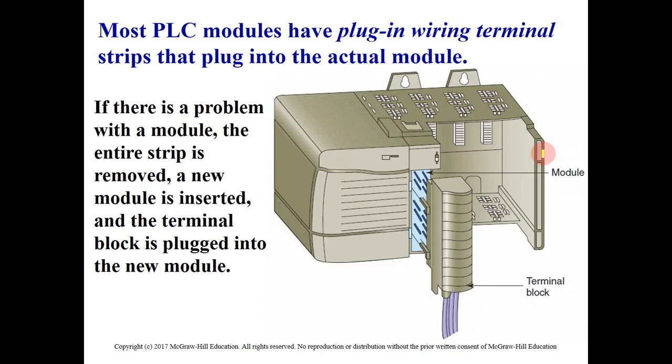This is just a 3D representation of the module, the modular PLC, and you can see here this is the empty place. In this empty place, we are going to plug in our module, the same as this one. This module already comes with the terminals and the wiring to the sensors or to the actuators. So it just plugs in inside this one. It will connect with the rear, in the back of this module or of this rack. It has a connection between different modules, either for input output, for CPU, for communication, for power, and so on. Also the power comes to the devices from these terminals or from these boards.